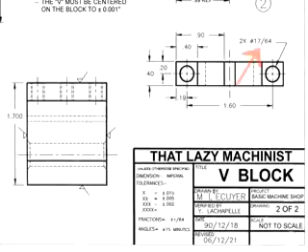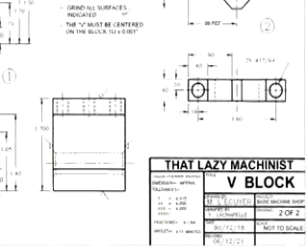As for this 17/64th fractional dimension on this hole, that indicates that I have a tolerance of plus or minus a 64th because it's a fractional dimension. And that means that this hole will be acceptable if it measures anywhere between and including 8 30-seconds right up to 9 30-seconds of an inch.